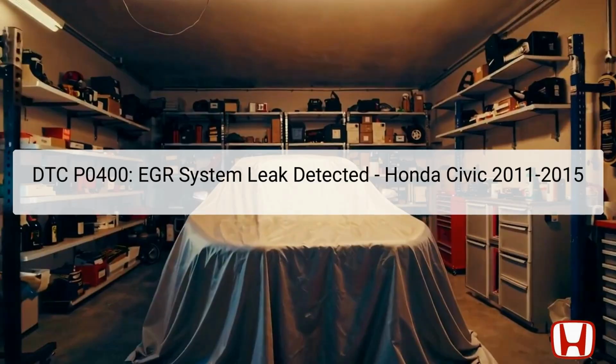The diagnostic trouble code DTC P0400 indicates an issue with the exhaust gas recirculation EGR system, specifically signaling a detected leak. The EGR system plays a crucial role in reducing emissions by recirculating a portion of the engine's exhaust back to the intake manifold. This process helps to lower combustion temperatures and reduce nitrogen oxide emissions.